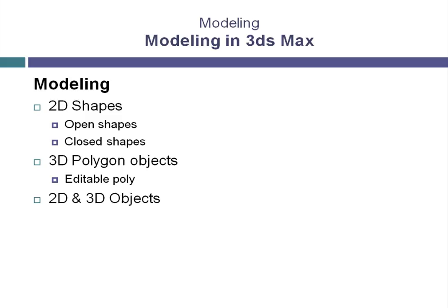We'll look at objects called compound objects, one of which will allow us to cut a 2D shape into a 3D object to define the edges of roadways. We'll look at using the graphite modeling tools in more detail so we can create our 3D objects and edit